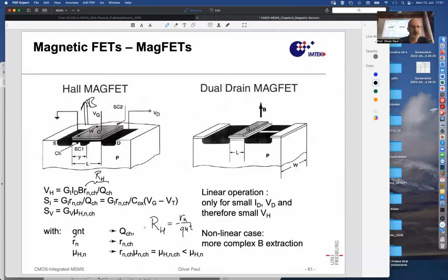It's the numbers of carriers. It's not the numbers of, it's Q times the number of carriers per square centimeter. So it's the channel integrated over the depth that gives you a number of carriers, and those have charge Q, and this is this channel charge density, as it is usually called.